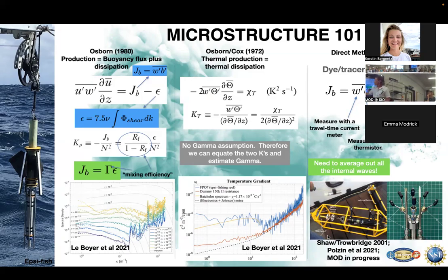They have these theoretical forms out to the small scales, and then noise always kicks in. So there's a lot of art and magic to knowing where it is okay to integrate all the way out to. But again, going to some of the theory that you guys have had, this vertical scale is called the Kolmogorov wavenumber, and that's the smallest scale where turbulence can exist. So that's method one.